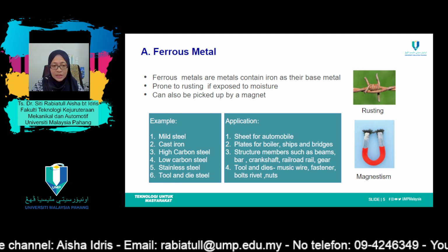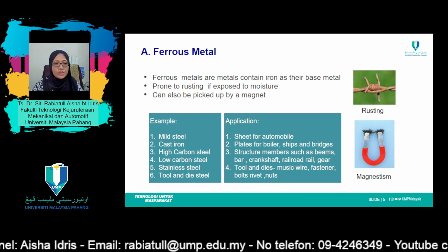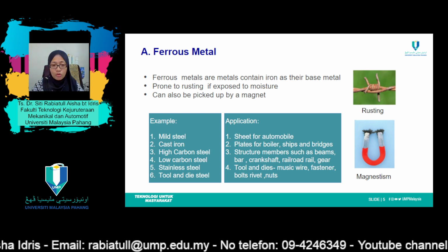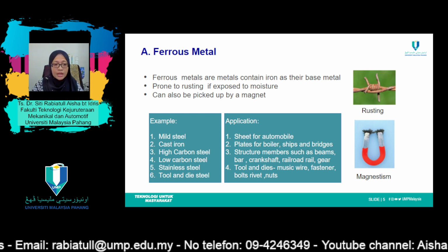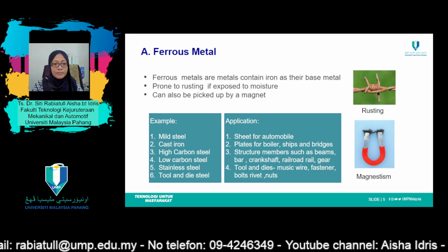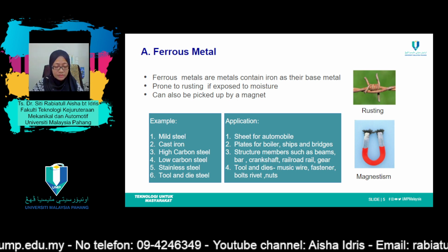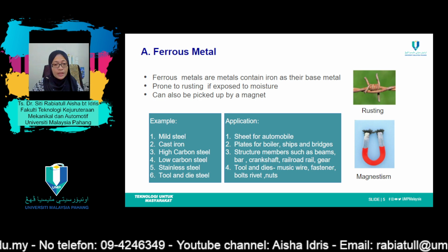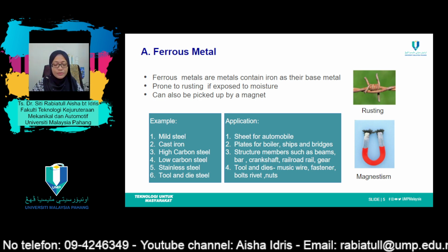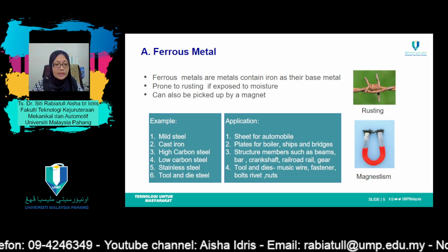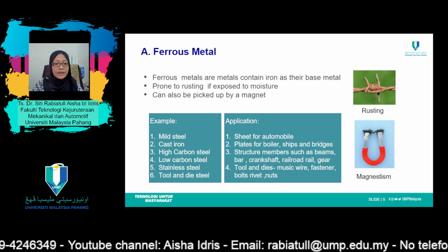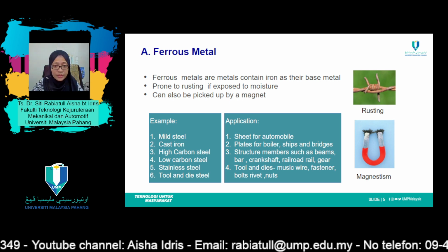Ferrous alloys or ferrous metals, those in which iron is the prime constituent, are produced in larger quantities than any other metal type. They are especially important as engineering construction materials. Their widespread use is accounted for by three factors. Number one, iron-containing compounds exist in abundant quantities within the earth's crust.